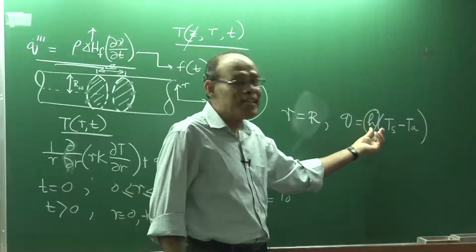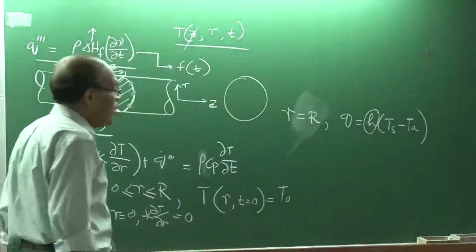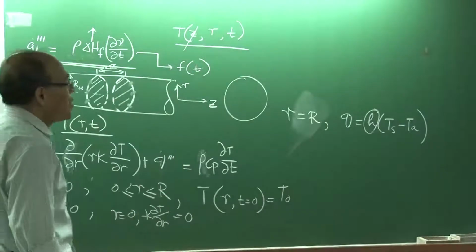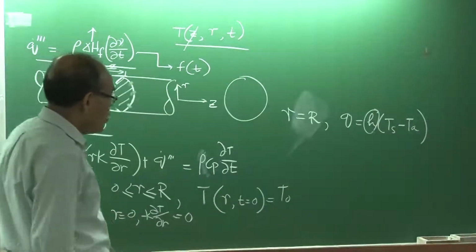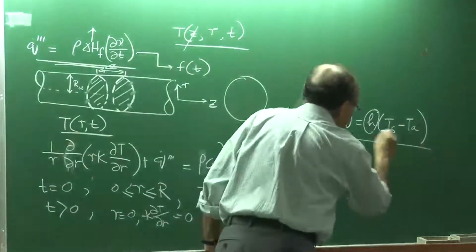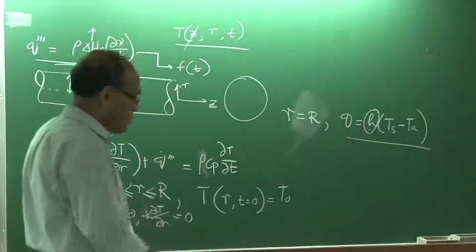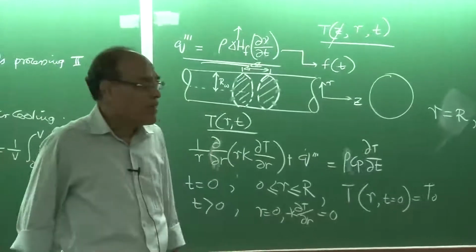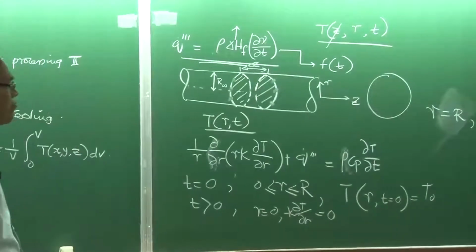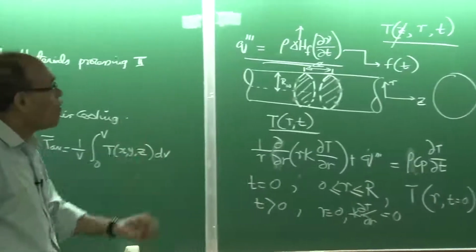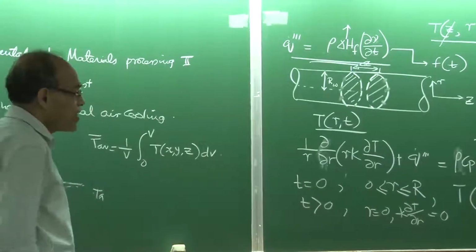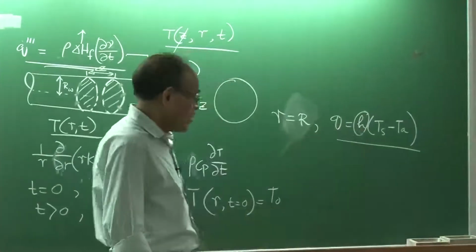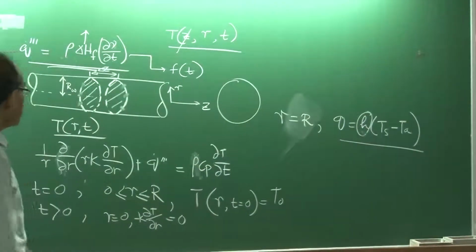That is what the intensity of cooling determines: the severity of cooling determines the heat transfer rate. Therefore, a forced convection boundary condition basically implies how intense it is. When you quench it, there is going to be a huge amount of stirring taking place in the vicinity of the solid surface, because you have bubble formation, etc. Boiling is taking place.